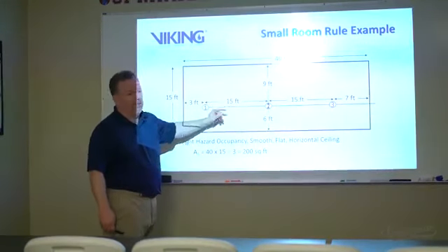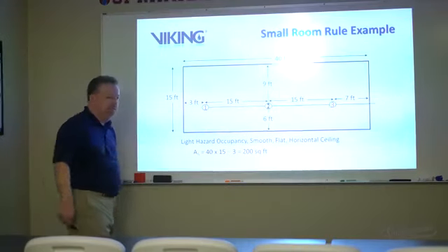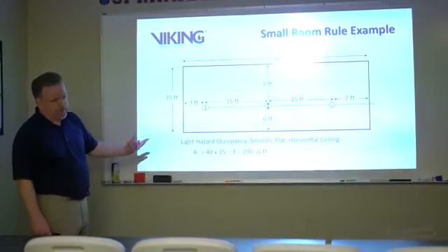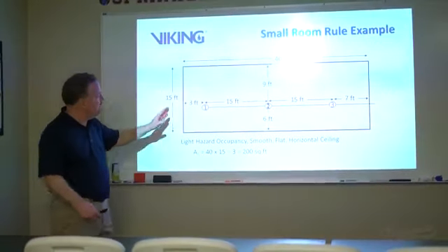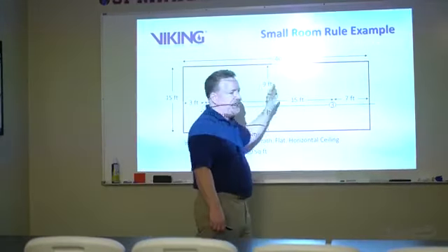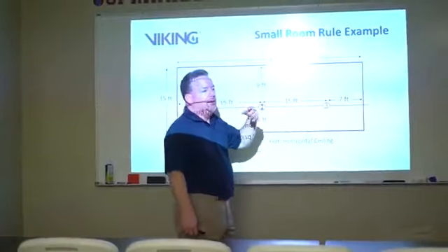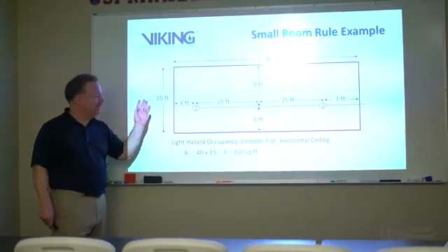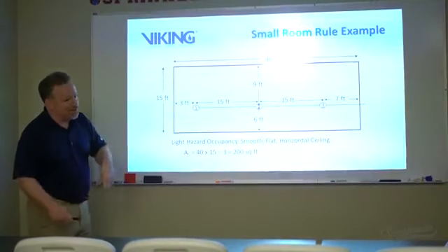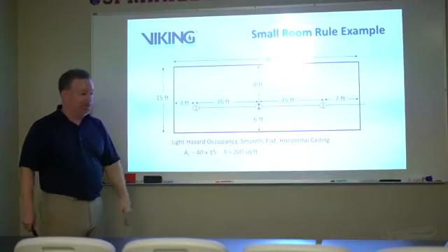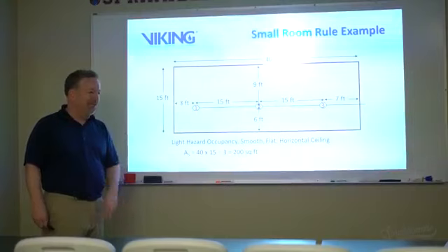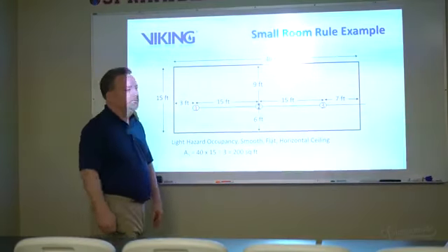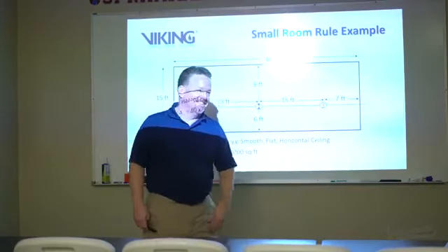Normally though, if you were to design that room, you could center them, potentially based on ceiling lights, ductwork. Yeah, things like that, potentially. But what you've got here, more importantly, is you've got 15 between each of these. So symmetry, putting the sprinklers in the right location, can also affect the aesthetics of the room too. I mean, you'd be surprised what you notice. Normally sprinklers are in before most of the other stuff. Usually, this would be a remodel probably, right?